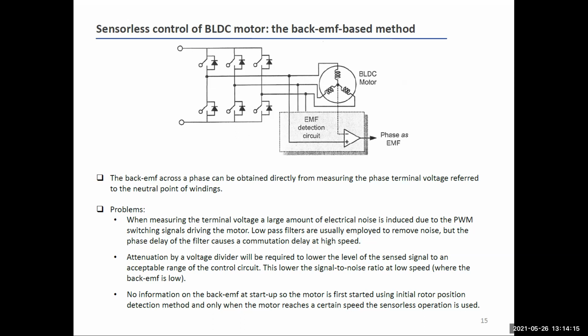But when you have a low pass filter to avoid the transitions at the switching frequency, remember that any time you have a filtering action, you also have a delay of the voltage or the current you are sensing. And in that specific situation, any time you have delays, you have an error, because the delay is exactly what you have to measure.